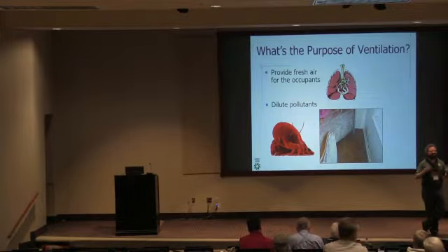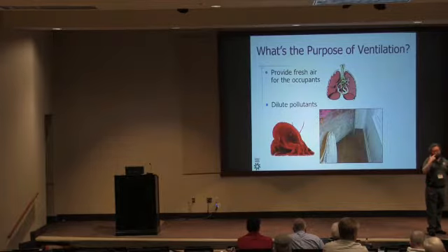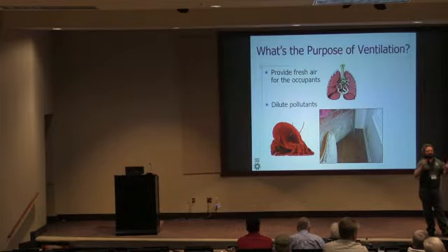And we're like, no, it doesn't. You don't want to maintain 70 degrees 24/7, 365 in your house, because your house doesn't need to be 70 degrees when you're not there, right? We're conditioning for human comfort. You can let the house drift up to 80 or 85 degrees and it's not going to hurt anything in the home. You can let the house drift down to 65, 60 degrees in the winter and it's not going to hurt anything inside the house. We are conditioning for human comfort. So it saves energy. Now, programmable thermostats can be a pain in the butt.